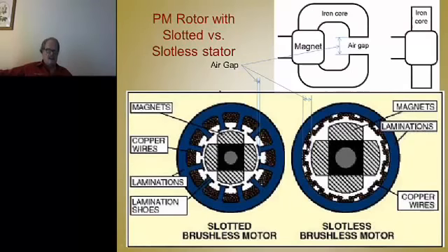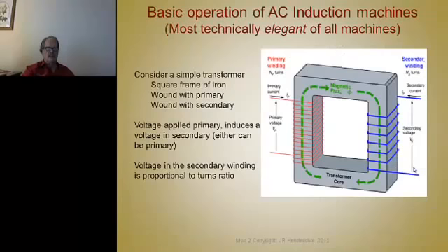As soon as it moves over here, I've got to change the polarity of the current in the new coil that's under that pole to keep it going. So this one's attracting and that one's repelling. When this moves around and covers these two coils, I've got to have this one repelling and that one attracting to keep it going in the same direction. So even though there are forces on the wire, according to the previous slide, there's still this attracting and repelling force. And to me, that's easier to get my arms around.